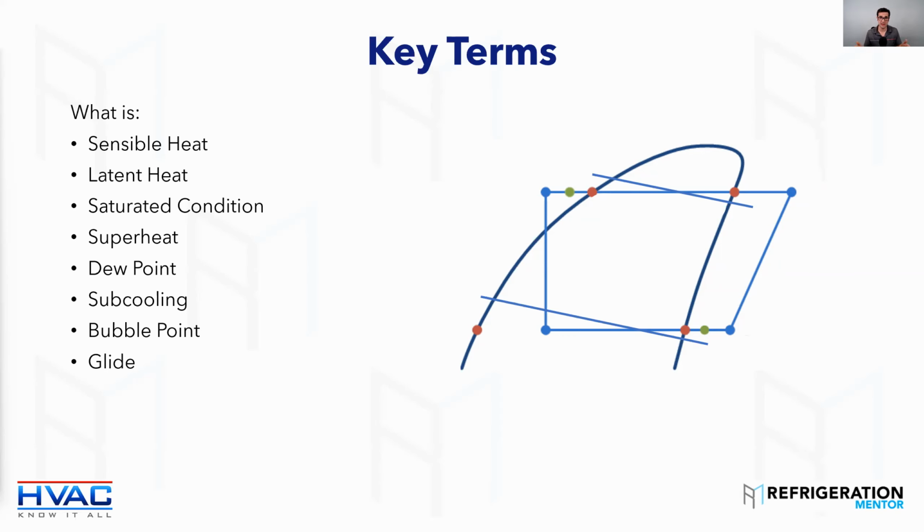There's like 15-degree glide in some refrigerants and some even higher. When we talk about newer refrigerants that have been out for many years, like 448, 449, you may have heard of them, they're between 8 and 10 degrees glide, I believe. 407A, 407F, 407C all have high glide. You may have heard of some of those refrigerants before, so you need to understand that.